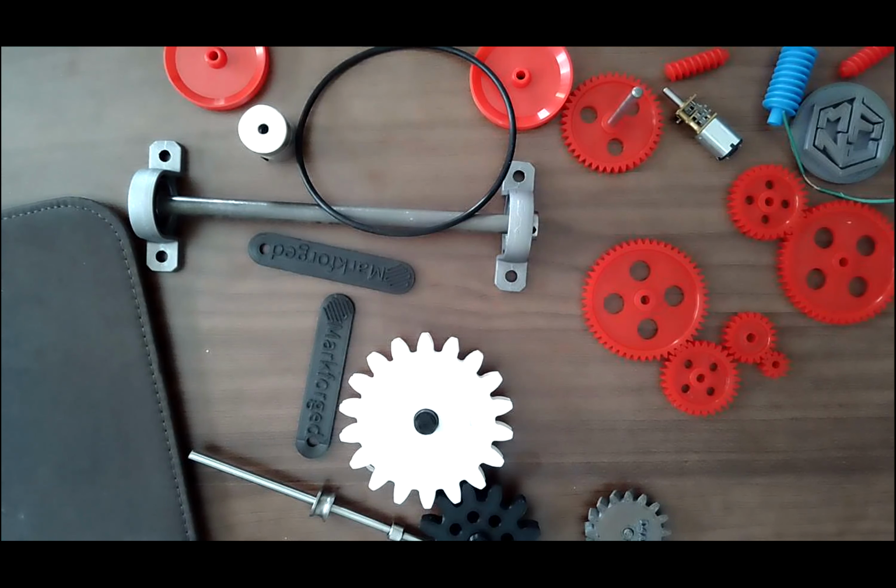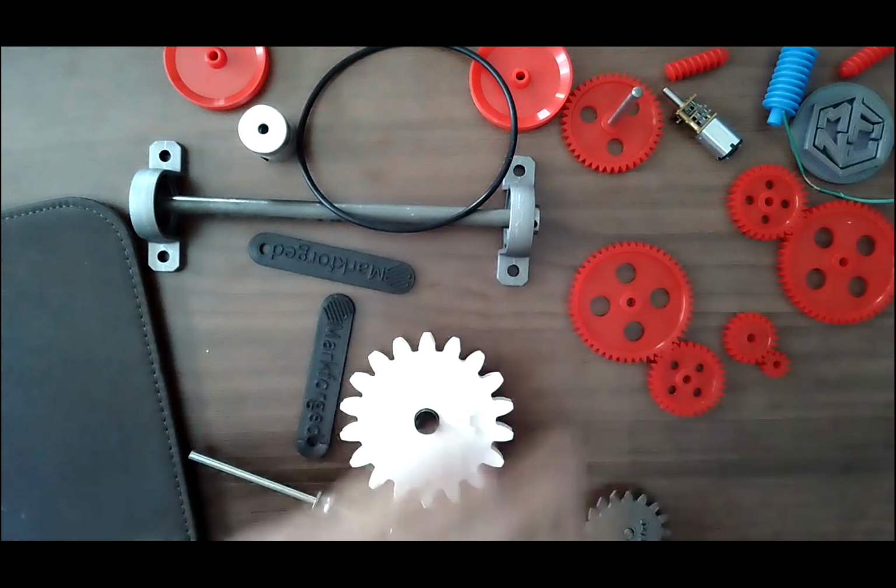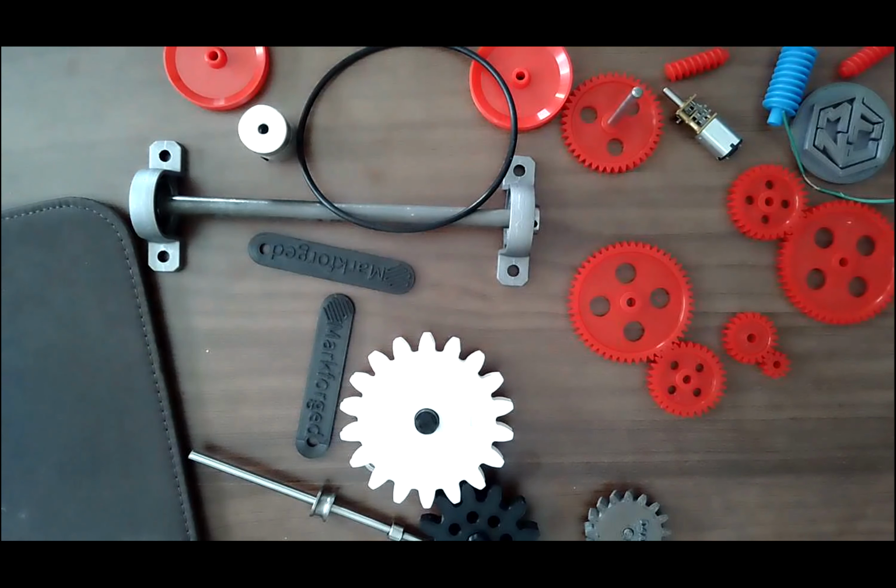Those are excellent, accurate gears, so they are super efficient. If they are lousy gears, the tolerance is not good, then the efficiency, of course, is not good. Of course, between gears there is friction and that loses efficiency. But as a rough number, you can think of 80% efficiency, which again, we'll talk about a little bit in formula. What do we mean by like 80% or 85%?